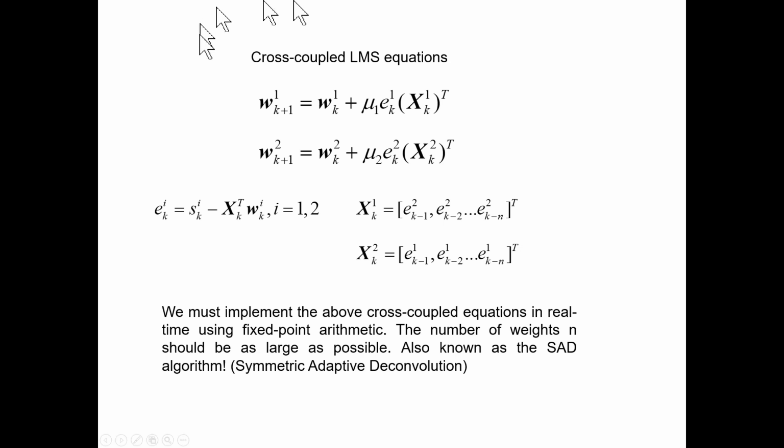These are the weights on the least mean squares. I'm afraid you have to understand least mean squares to know this, but mu1 and mu2 are gains, which you'll see when we make the thing itself. We can make them the same, mu1 equals mu2. If you make them too big, it won't work; it'll become unstable.